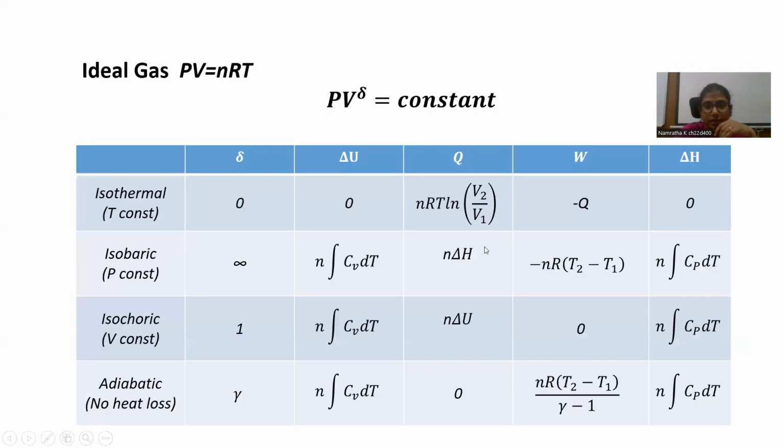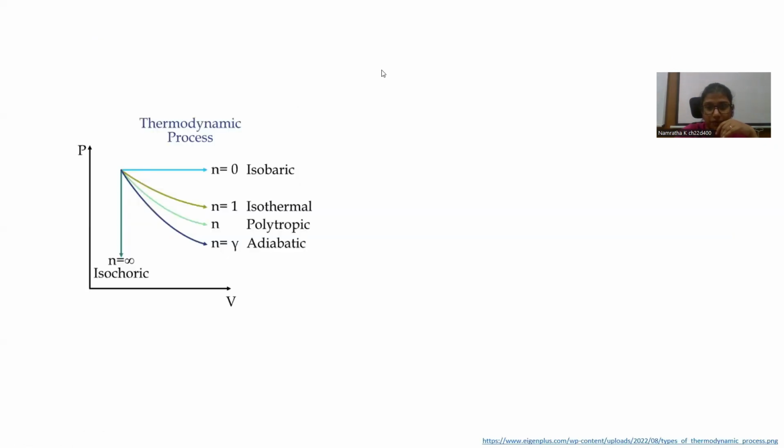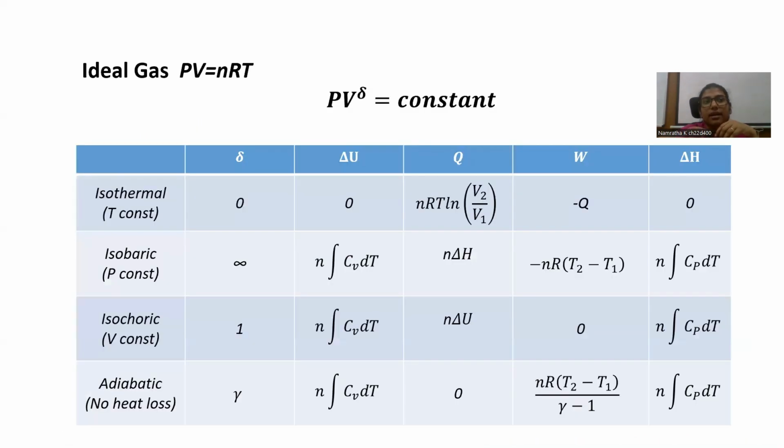Here we can discuss that ideal gas behavior is a very approximate way of assuming fluids. So this behavior is possible only at very low pressures and high temperatures, where we can assume that interparticle distance is very high.